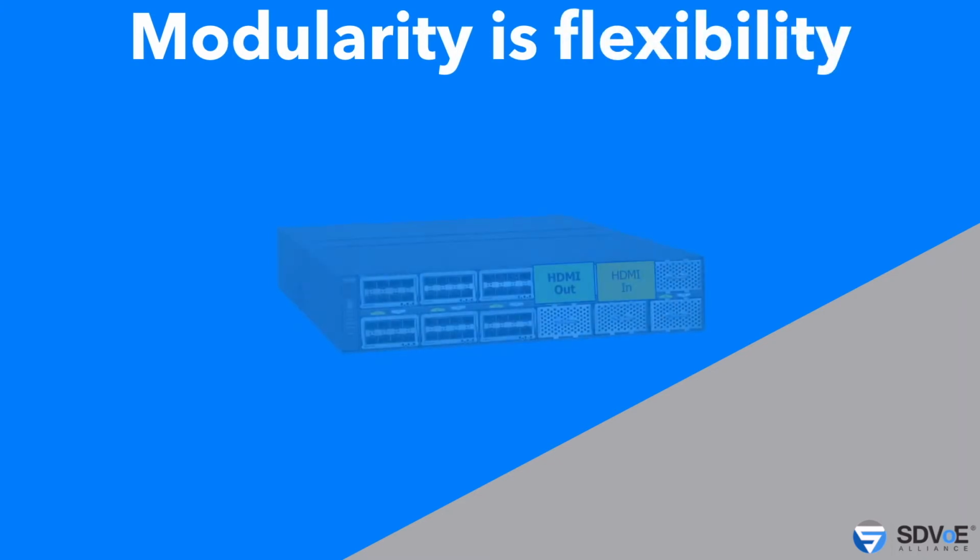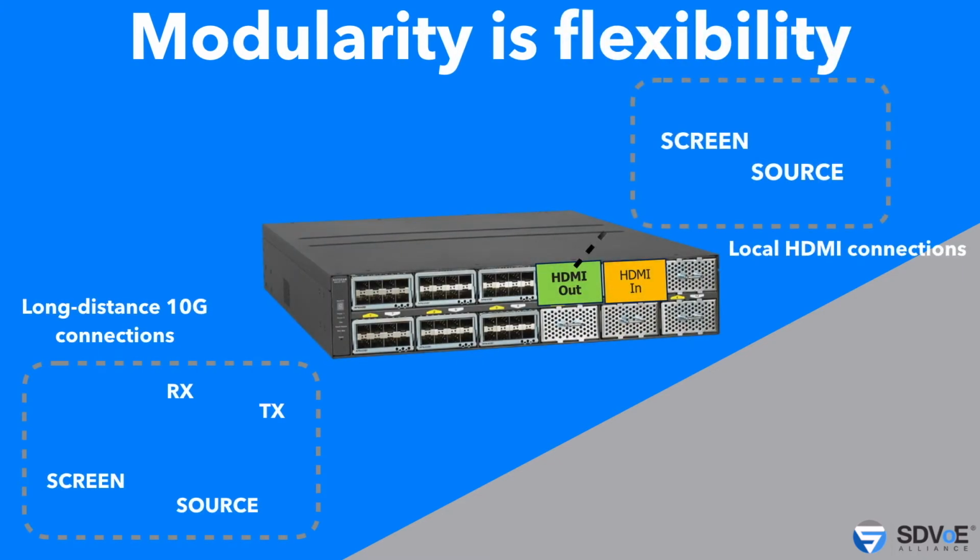One advantage that the matrix switch has traditionally had over AV over IP is its modularity. Right, today when you guys think of a matrix switch in Pro AV, you're really thinking about a big empty box with some card slots that aren't filled yet, right? And that's because we recognize that designers need different complements of ins and outs for different jobs. So you buy a chassis and then you put some HDMI cards, some HD-based outs, some SDI cards, whatever mix and match you need.